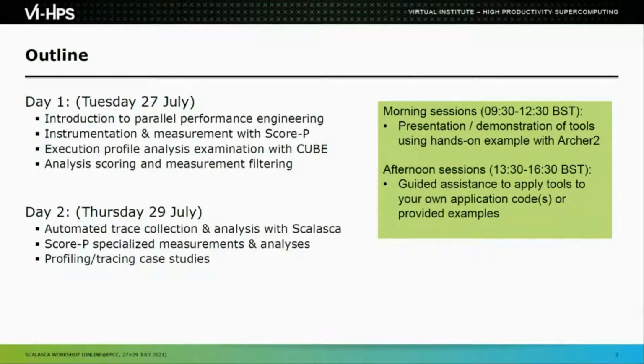If you're running for days and days, it's quite conceivable that your simulation performance is changing as the data is evolving, as you have shock fronts or other characteristics that are not necessarily happening at every time step, or that are growing and spreading out through your simulation domain. So either you have a longer profile that has everything aggregated together, or you split that into separate profiles where you're looking at each phase of execution, the first few hundred time steps, and then some 100 time steps closer to the end. If they're very similar, then great, you don't have to worry about the differences. But if you have a simulation that's changing with time, then you need to be careful about how representative the time steps you're looking at are of the longer execution.